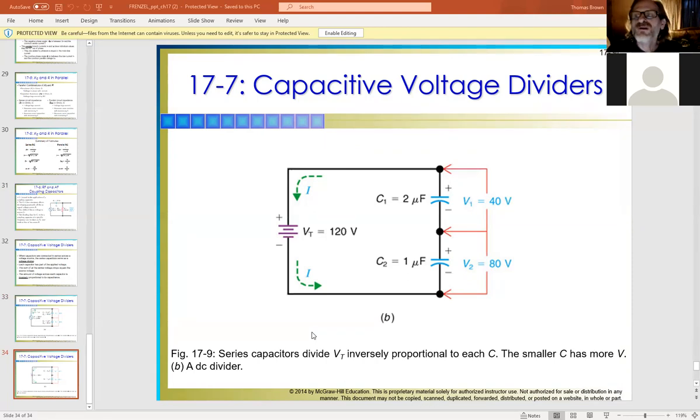Thursday's lab will reflect that, and we'll keep going with this. But it's pretty straightforward, as long as we recognize what the capacitor's doing and what we expect. We always know that the minute we throw a capacitor in there with an AC signal, it is always going to have that negative 90 degrees associated with it. The resistor does not cause any type of phase shift. And then our basic rules still apply: what happens with a series circuit, and what happens with a parallel circuit.